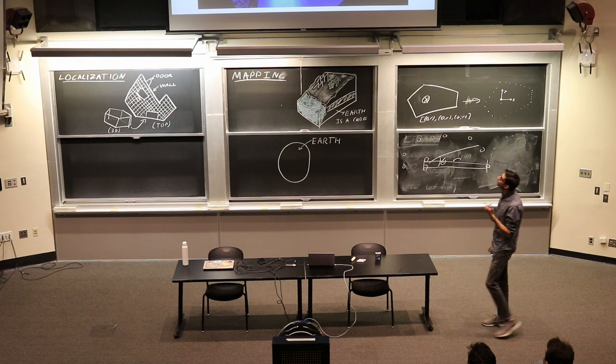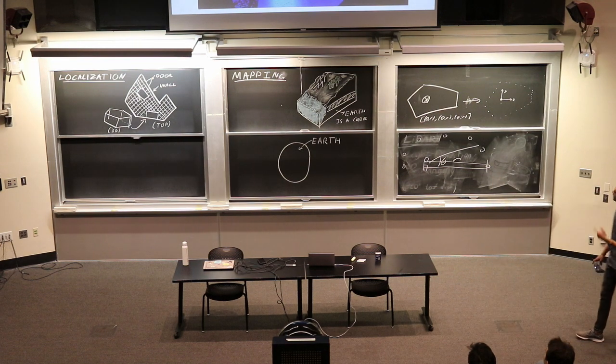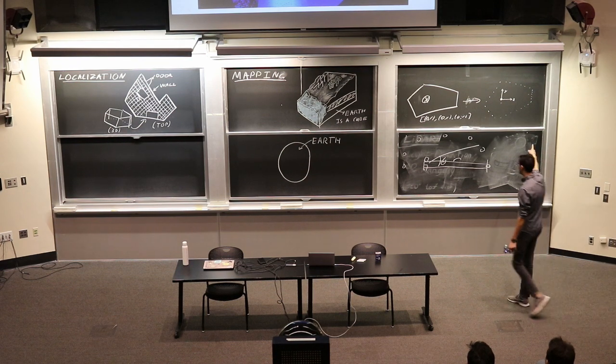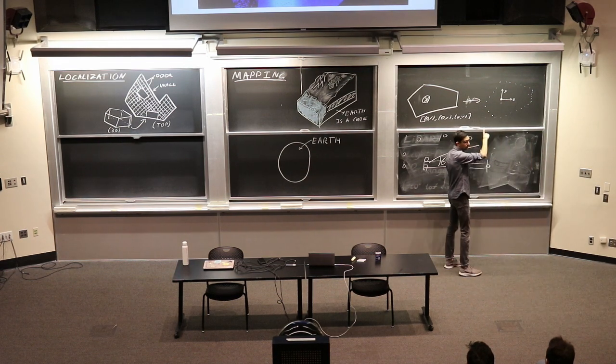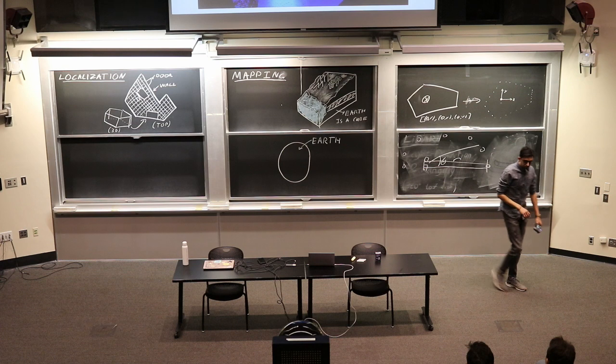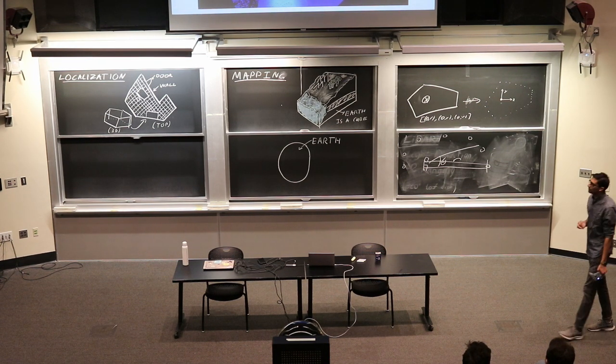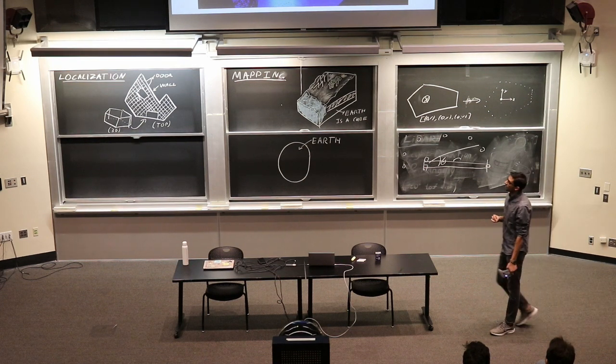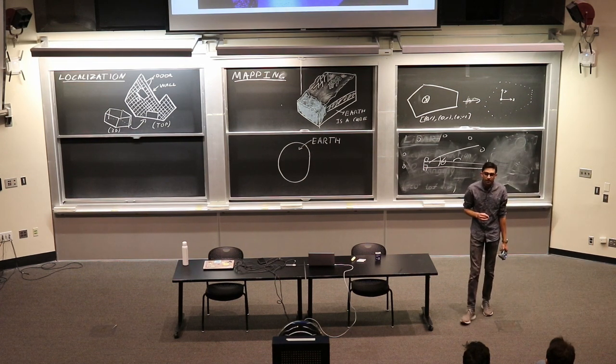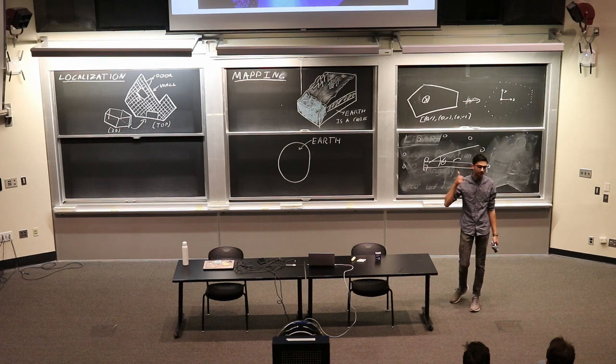Yes, and this is a super detailed LiDAR point cloud. You'll probably see the LiDAR point clouds that you're going to get look something like this with some more points. But this, I believe, is from a Velodyne 128-channel LiDAR, which means there are 128 lasers on this LiDAR sampling at something like 1,000 hertz. So this is a ridiculous point cloud.